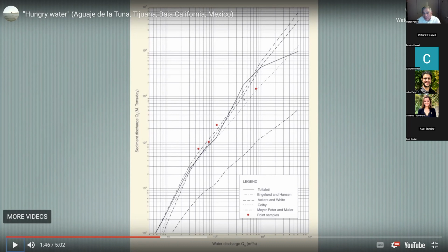Notice also that if you want to look at the M value, the M value over here is high and over here is much lower because it kind of went up this way. So my guess would be that over here the M value is high, maybe 5 or 5.5, and over here is more like 3.5. So this is a typical as measured and as calculated sediment rating curve, and it shows the variation of M locally. M, the value that we were discussed when we discussed the modified Lane relation. Always carry under steady equilibrium conditions.